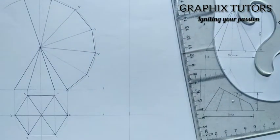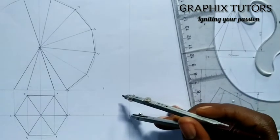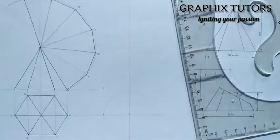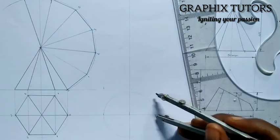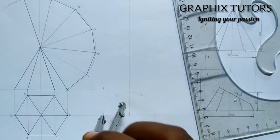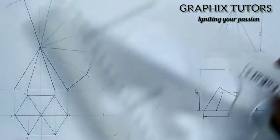Come to this point. I'll draw my circle, faint line with the same radius. I'll place it here. I'll bisect up and down. Come here also. I'll bisect up and down. So we're going to join them together.